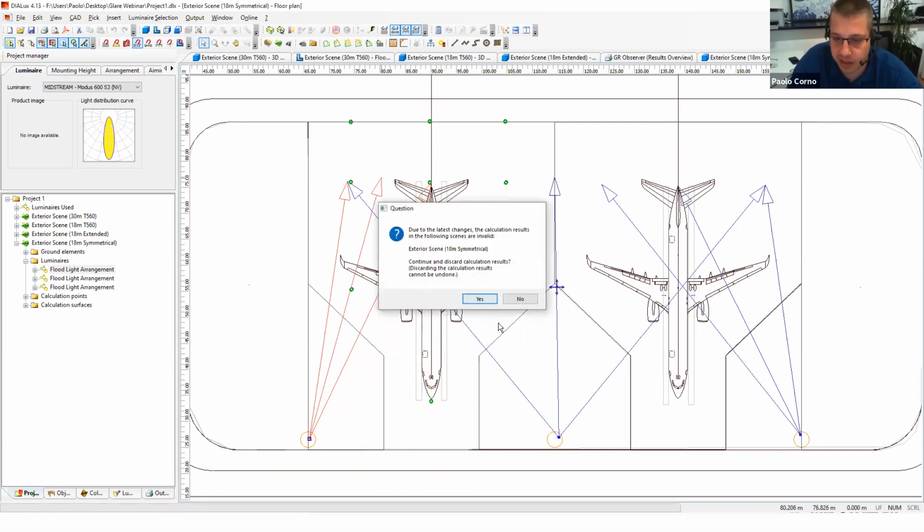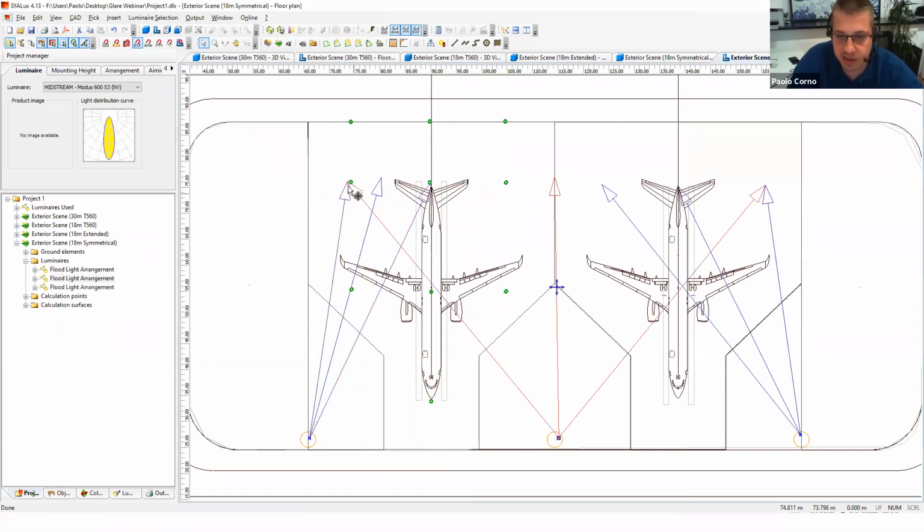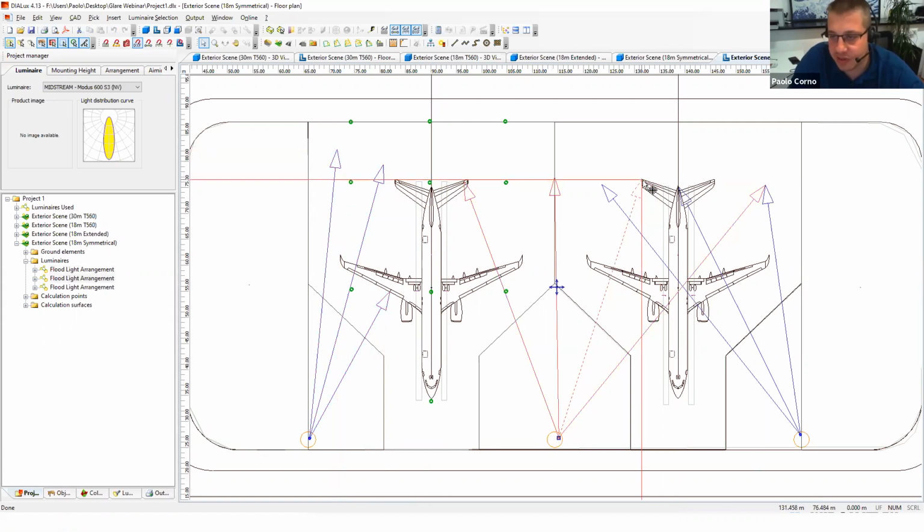So for example here, in order to reduce the value, we would try to avoid luminaires crossing their beams on top of the plane. We'll try to keep them in their area as much as we can. But of course, the result is always going to be that I'm moving the glare somewhere else. But sometimes you're left with no choice.